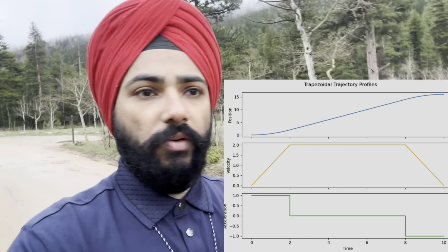What if the initial velocity is in the negative direction, or the positive direction? What if my constraints are unrealistic? Maybe I put an acceleration limit of 0, and I'm expecting that the vehicle should start from a position and go to another position. Obviously, my system should give me an error and say, hey, I can't compute this trajectory. So I came up with 60-odd test cases, and I did all of them in MATLAB. I generated plots for each one of these and made sure that all of them were covered.